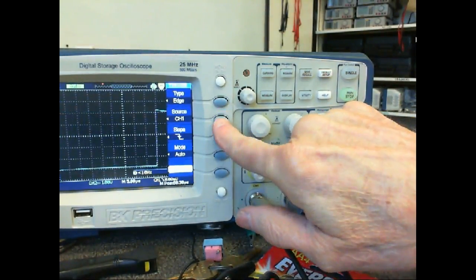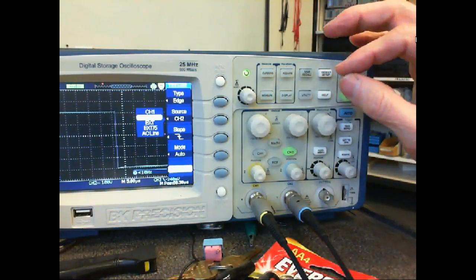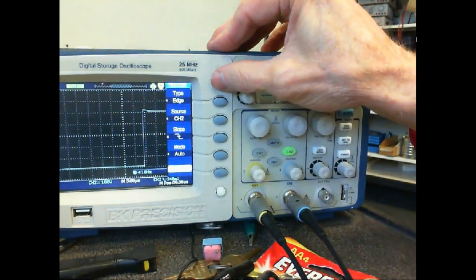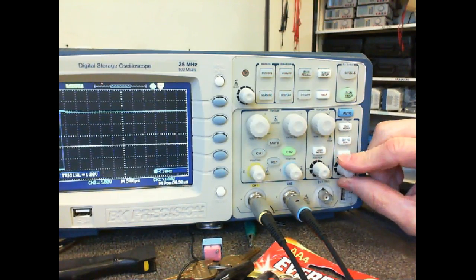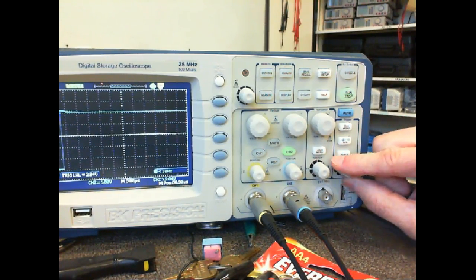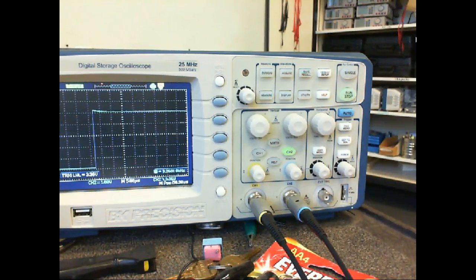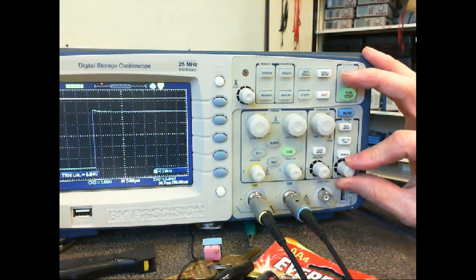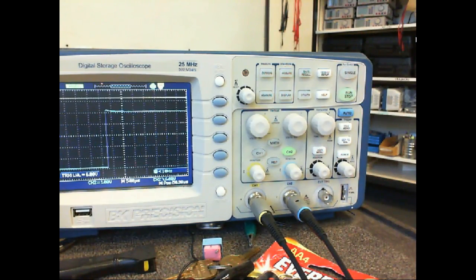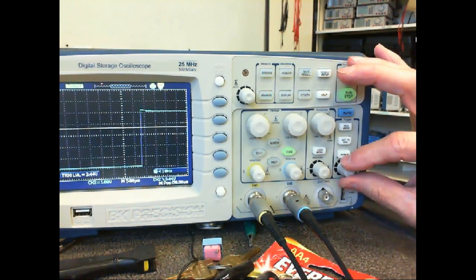Well, I'm not using channel 1, so I need to change that over to what? Channel 2. And then what we need to do is set what we call a trigger level. If y'all can see the white line moving through there, we just set it inside the waveform somewhere. It can be anywhere. It's just when I get it out of the waveform, now it's not synchronized anymore, right? You understand? All you got to do is get this guy down inside the waveform itself.